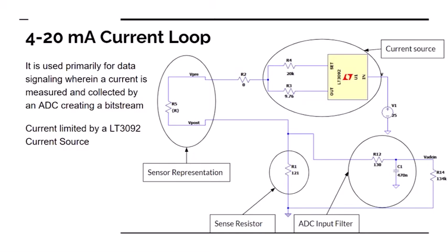Current sources are useful sensor architectures as the current flowing is used to power the sensor, so additional power supplies are not necessary at the sensor's location. There is also decent noise immunity as the current loop is low impedance.